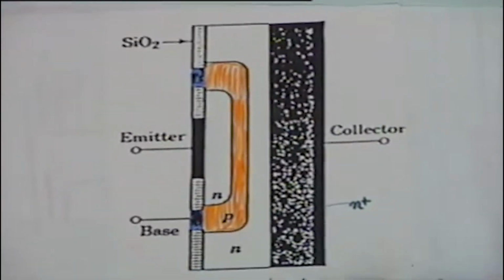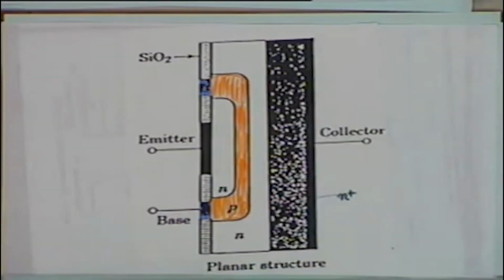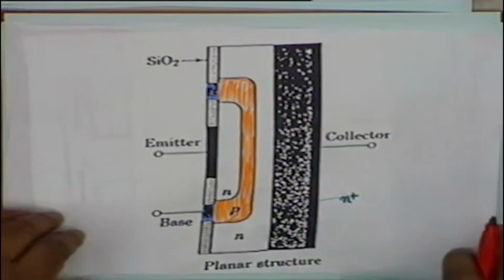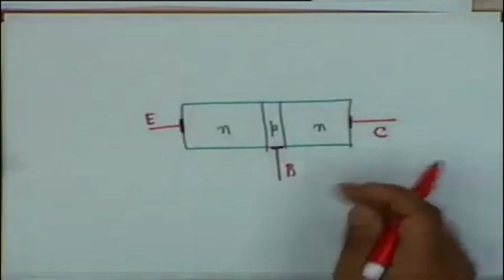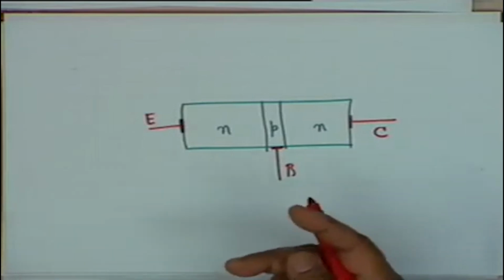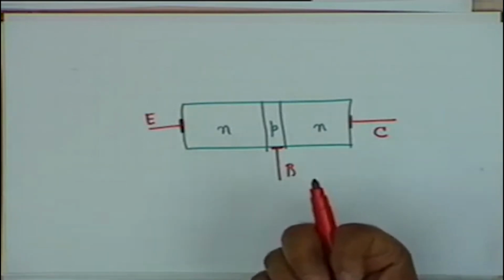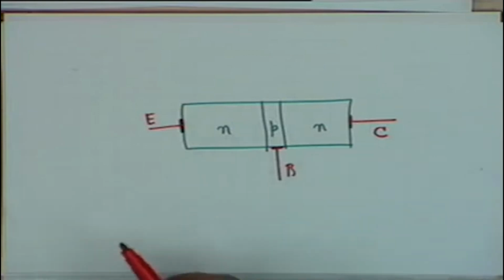This also shows, it is an interesting question, that if the collector and emitter are interchanged, in theory, if I give you a schematic like this, there is no reason why C and E cannot be interchanged. But the fabrication is such that if you interchange them, then the capabilities of the transistor, the power handling capabilities, become limited.